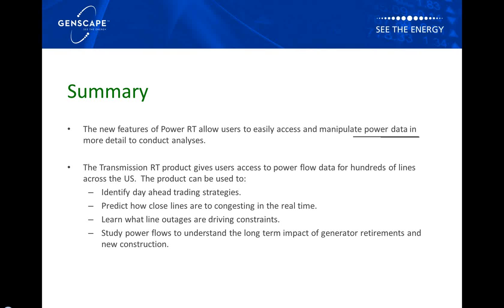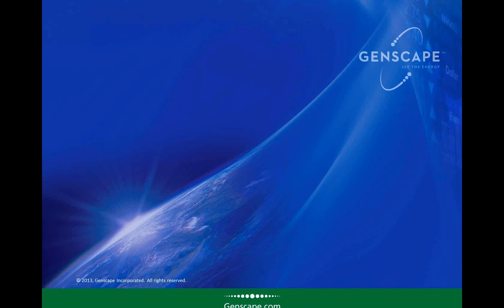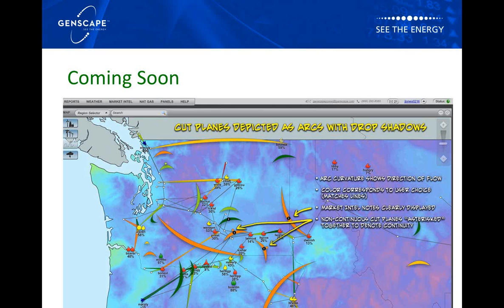And you could also identify that, if you looked at the flows between PJM and New York, you could see that they had gone from about 300 or 400 megawatts flowing into New York to about 1,200 megawatts flowing to New York within an hour. And so we were able to use all this data to really understand where this congestion was coming from. So you could see the really strong flow on Roseland Whippany combined with some strong exports to New York.